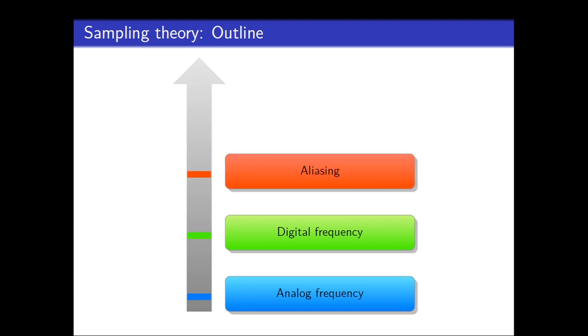Following this, we must identify the best possible sampling rate for a given system or given analog signal. The reason is that an inappropriately defined sampling rate may cause aliasing, which is a loss of information. So we must ensure that whenever we sample a signal, we sample in such a way that we can recover it back after processing. For that, we should identify the best sampling rate without aliasing.